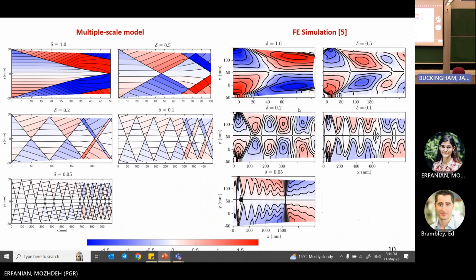And I think the interesting takeaway from this result is that although all of these are the same material with the same initial thickness, you can see the intensity of shear stress is different, and this may affect the hardness of the sheet. So I'm not saying that this model can predict the hardening, but I'm saying that it seems that this oscillatory pattern may have a connection to it.